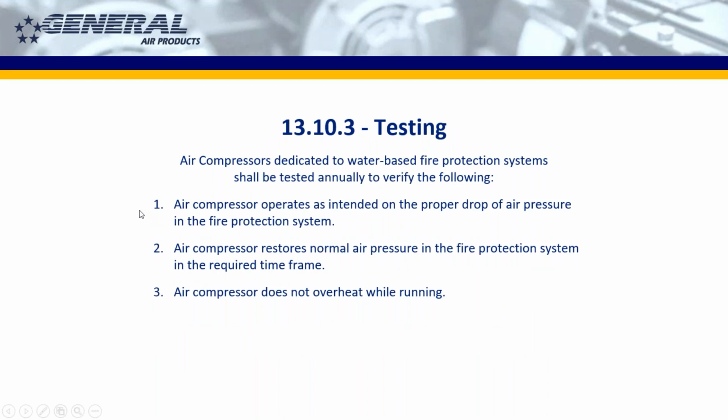To test them, you now want to make sure that the compressor operates as intended with the pressure drop. So you try to make a pressure drop or allow some of the air to bleed off, and then make sure that it turns on at the right pressure and turns off at the right pressure. It's going to restore in the 30-minute time frame, and it doesn't overheat while running. Overheating is a little difficult.